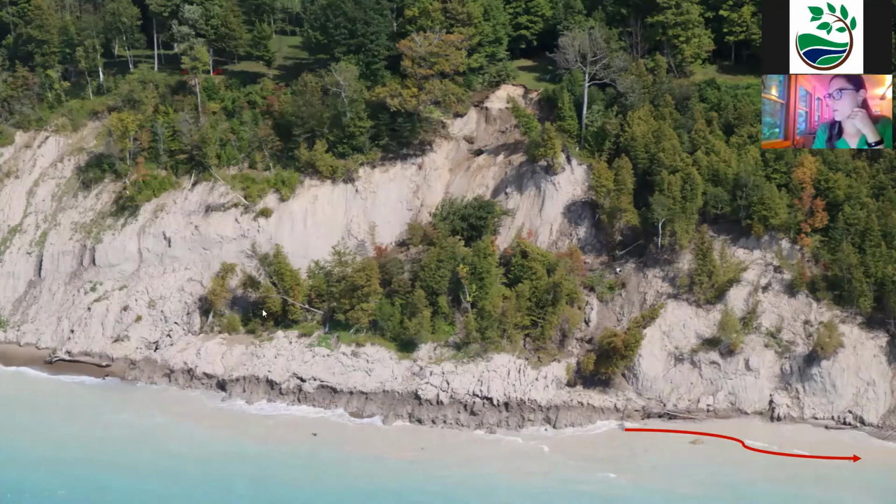And maybe a misconception is that people think once these failures happen that it will kind of recreate that plug at the bluff and hold it up in place. But since the soil is so disturbed, now it's more vulnerable to getting eroded and moved offshore and downdrift. And in this photo, you can actually see the water is pretty blue on the side before the failure. And then on the downdrift side, you can see that the water is really murky, and that's because the water is just eroding away that sediment. And we would expect for this cycle to continue throughout wet conditions.